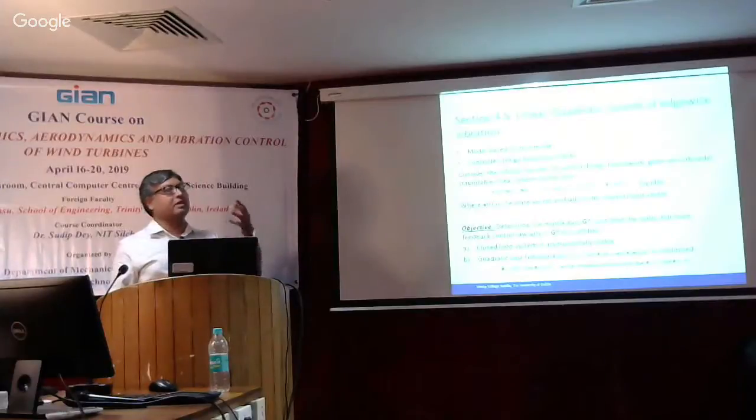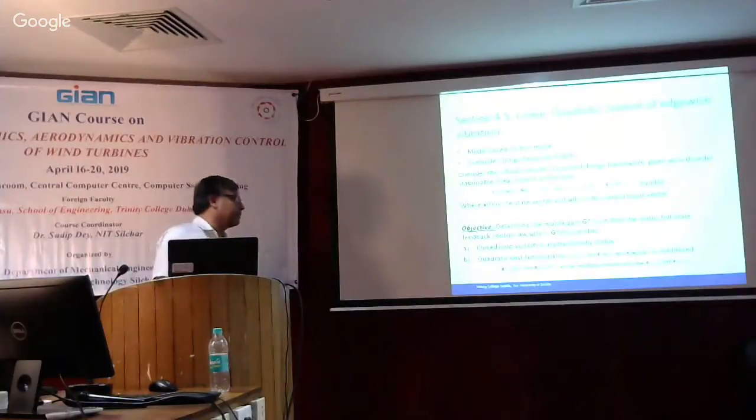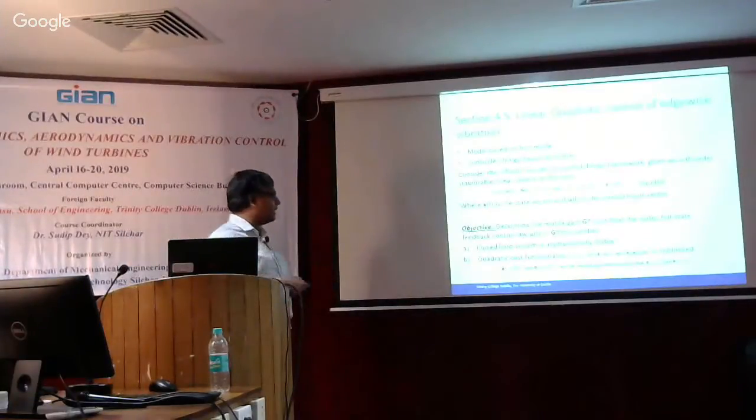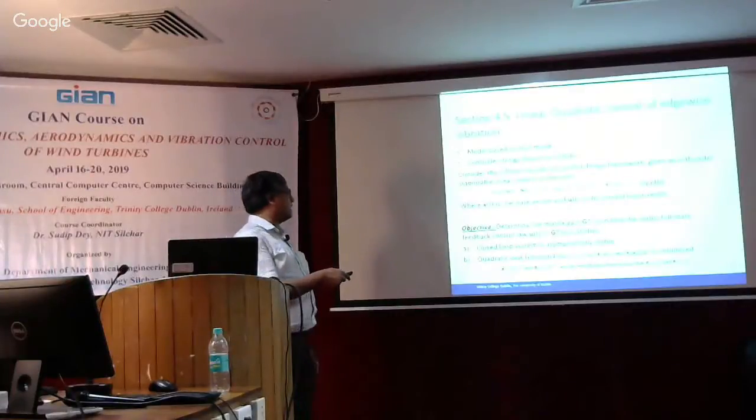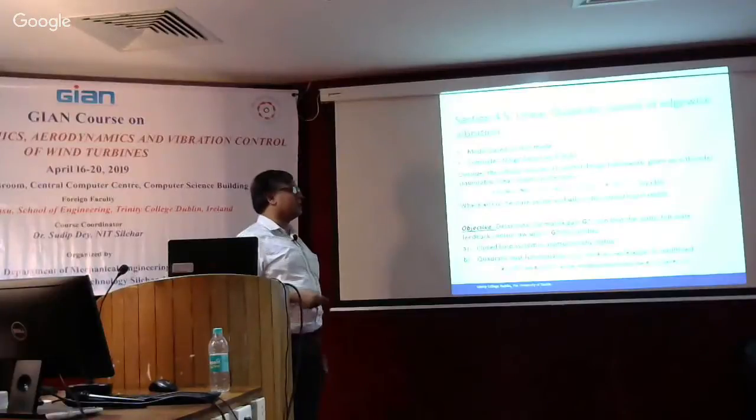So we have to derive the x and x dot from, maybe, if you have an acceleration measurement, then you have to integrate it once and twice to get velocities and displacement respectively. And once you have that, then you apply another matrix to it, and that gives you the force that needs to be applied to solve it.